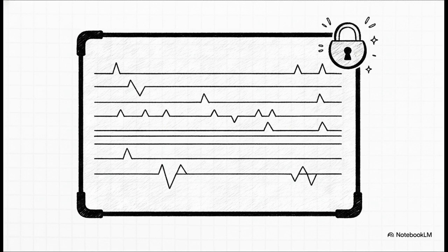Now, pro tip, before you do anything else, go to File, Save Format, and save this layout as wave.do. Do this so you don't lose your specific window arrangement and have to manually drag and drop your signals every single time you open the project.